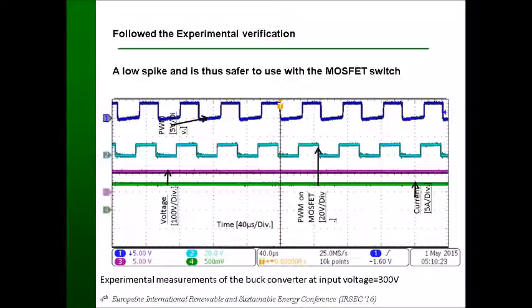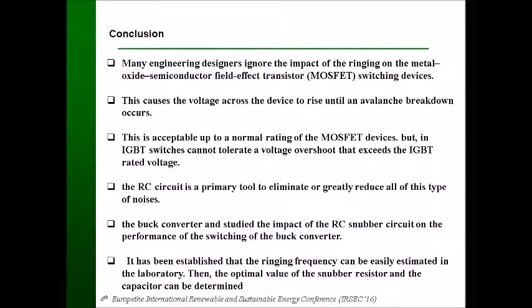Also, I tested the pulse width modulation on the MOSFET and from the generator, and on the MOSFET it was noted that there is some tail time.